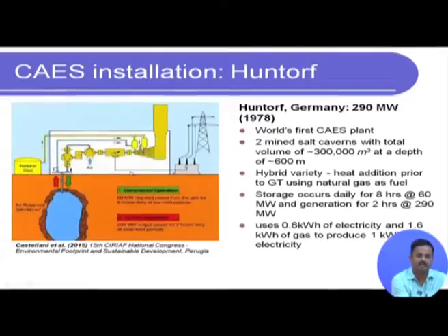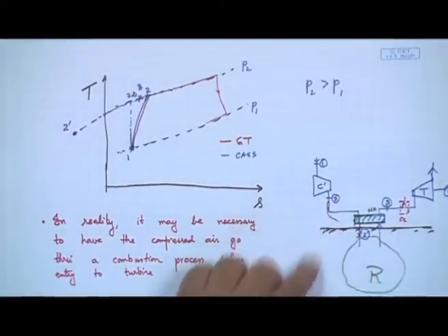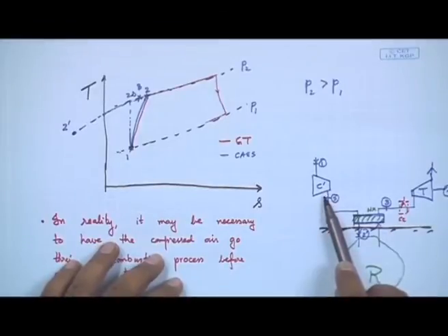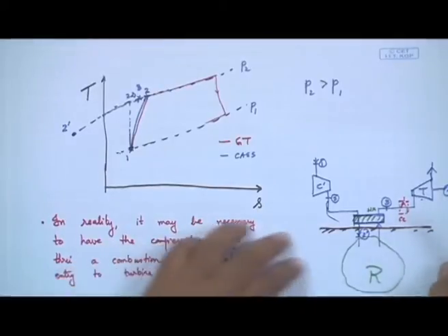Okay. So, you have first one turbine, then again another combustion, and again a second turbine, and from where we generate the electricity. Okay. So, what do we have compared to the simple diagram that we drew over here or even here, for example? What we have actually is a two-stage compression and a two-stage expansion. Clear? And between the two-stage expansion there is another combustion chamber. So, if I have to again draw it schematically, let me keep it here and let me quickly draw what is happening. It would look something like this.